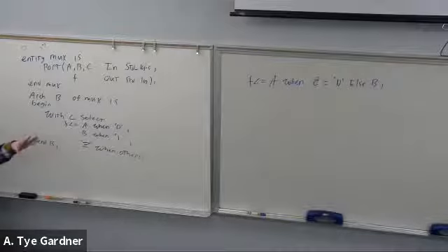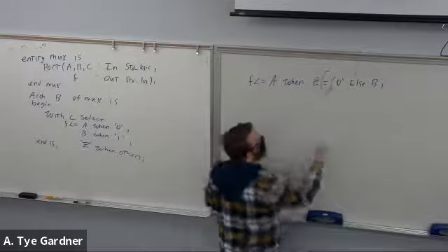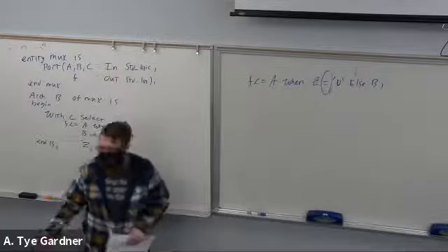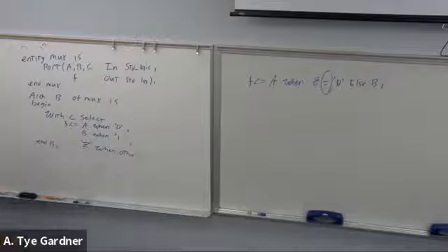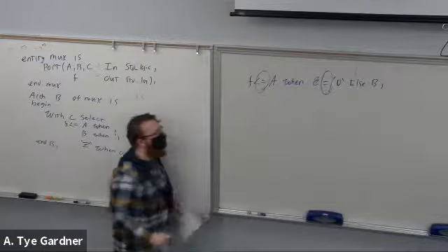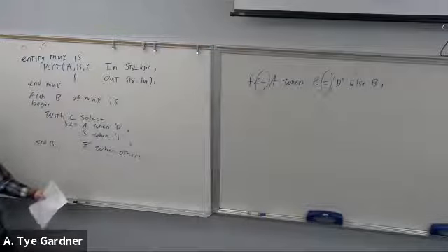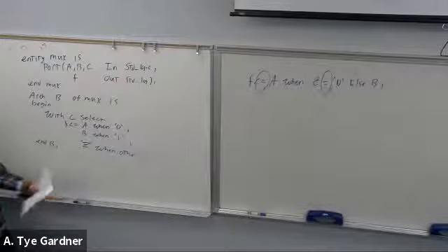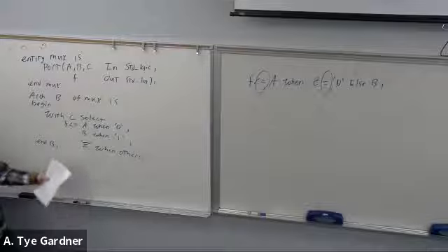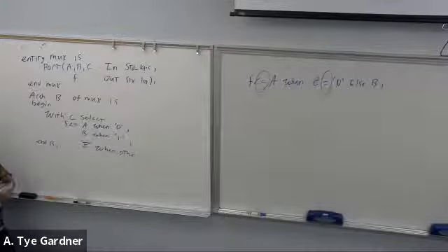Well, that has the same potential problem with C, right? So remember, this equal means it's a comparison. It's asking the question, is C equal to 0, right? Whereas this equal is the assignment statement. So if C is 0, it gets A into F. But if C is Z or X, it gets B. We can fix that with more else statements, totally fine, works great.